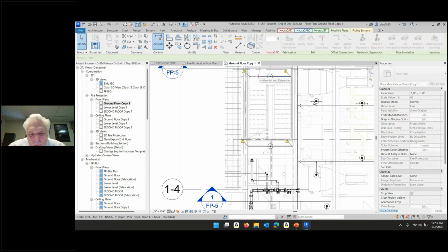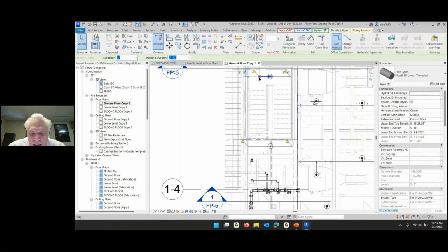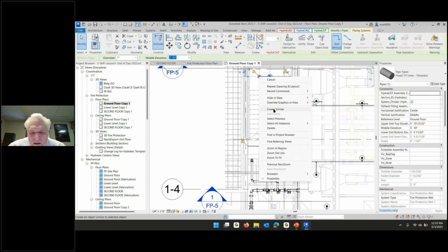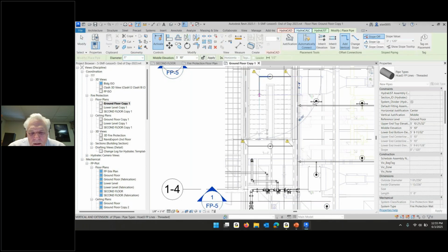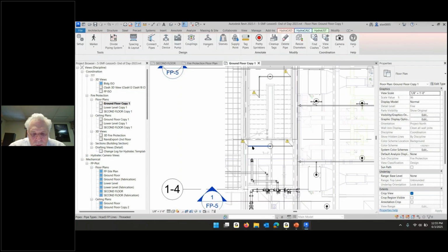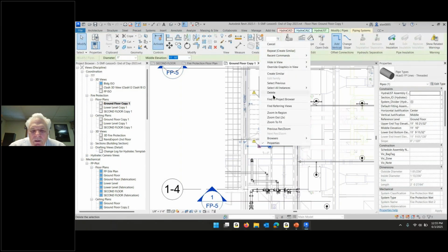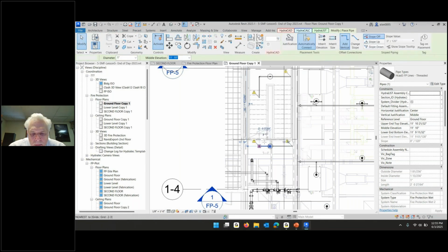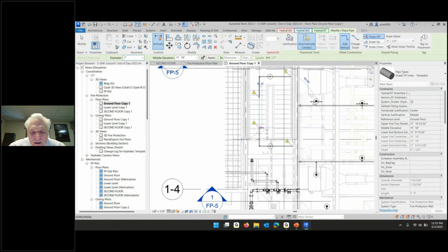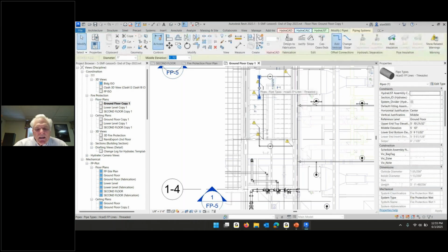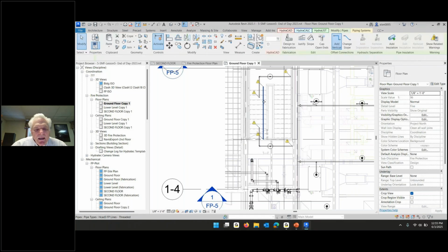I'm going to drag this pipe back, right click on the end and say draw pipe, or create similar will do. That gets me into the slopey part of the stair. I'm going to take this pipe and drag it back till it lines up with that one, and then right click and say create similar and get started in there, escape, and I'm going to draw another pipe parallel. So this one's flat at 510, this one's flat at 1110, and this one's flat at 1110.